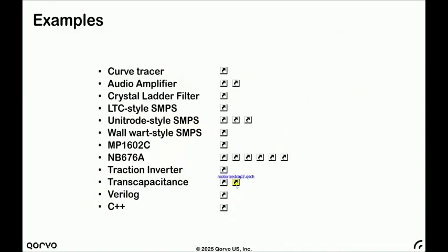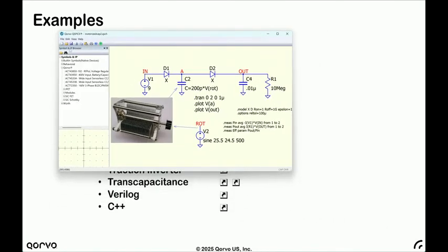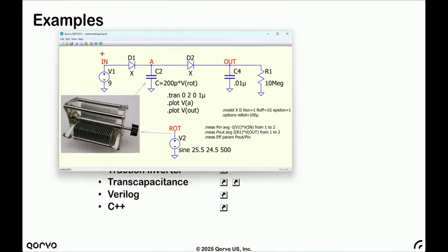I don't know if there's any real SPICE aficionados here, but people who know SPICE know that if you're going to write a charge model that's complicated, as involves transcapacitances, you don't want to write the equations in capacitances, you want to write it in charge. That's the only way to conserve charge in your circuit, okay? And that's why BSIM is so much more complicated than MOS 1, 2, and 3, because it has a charge-based model instead of a capacitance-based model. And in the 80s, you would take Berkeley SPICE, replace the charge model, go around all the semiconductor manufacturers and say, look at your SPICE, look at the circuit, see that gate voltage is dropping off to infinity. Now, however, if you run that circuit in our simulator, it doesn't run off to infinity. Your simulator doesn't conserve charge. That's why you pay us $50,000 for our simulator. That was the business model in the 80s for SPICE houses, okay?